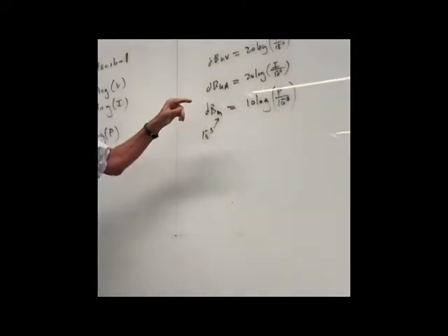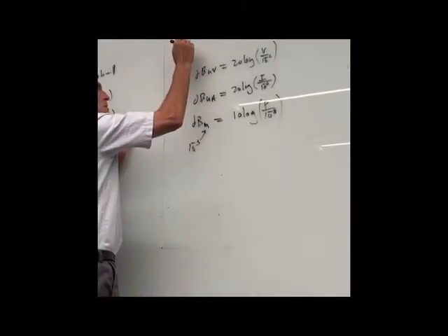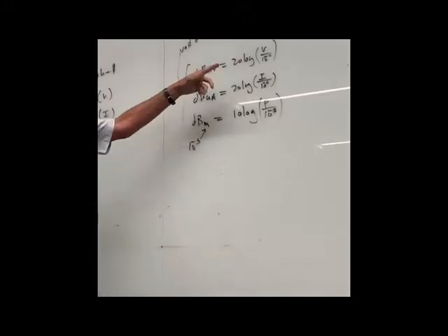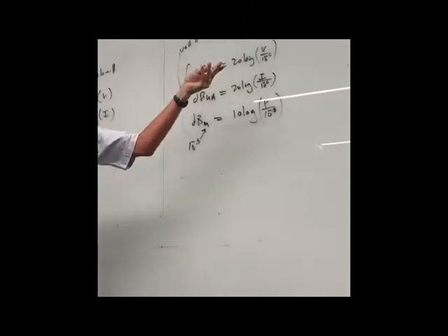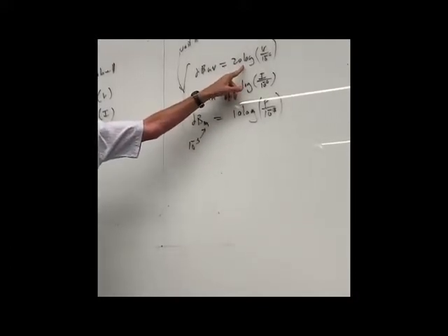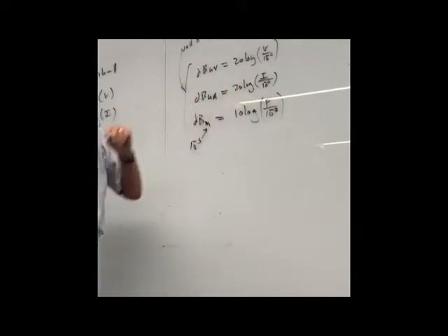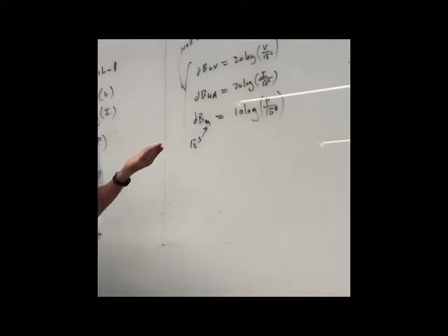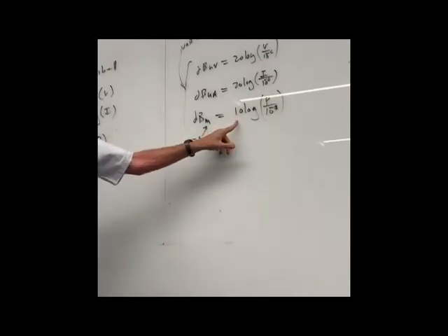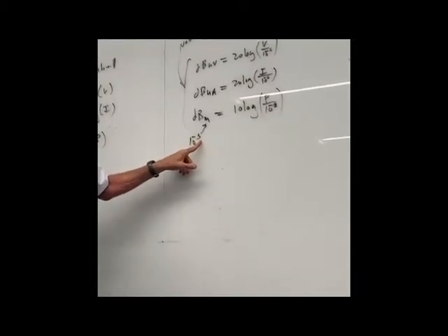So you can really see the trick here is that these are all units. When we talk about dB microvolts, micro indicates 10 to the minus 6, that's the reference. Since it's a voltage, you have a 20 in front of this. These are all log base 10, by the way. If we're talking about dB microamps, it's 20 times the log of I over 10 to the minus 6. Again, the micro indicates the scale factor. If it's dBm for power, it's 10, because it's power, times the log of the power over 10 to the minus third. The m indicates the scale factor. Follow me on this, guys?